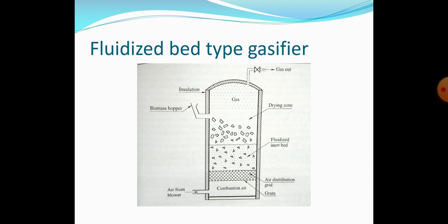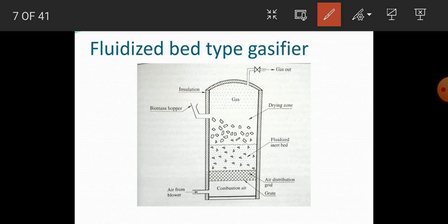fluidized bed type gasifier. So, this is the most versatile, and any biomass, including sewage, sludge, pulping effluents, etc., can be gasified using this type of gasifier. It provides a means of burning any combustible material from wet sludge to refuse with high efficiency and with minimal pollution.